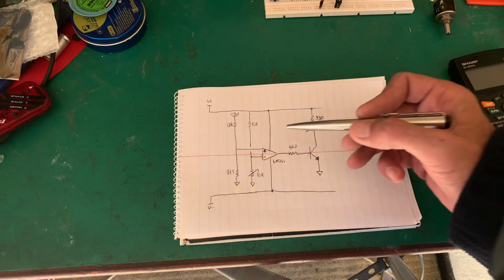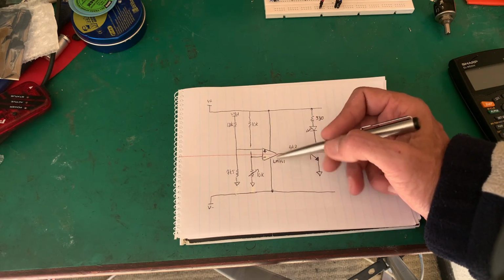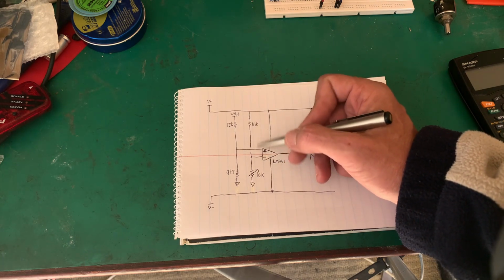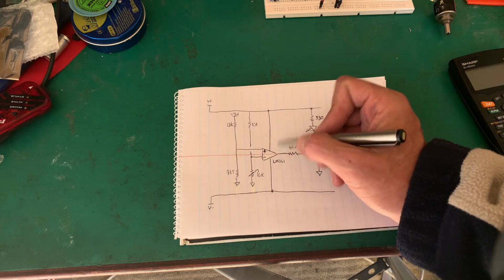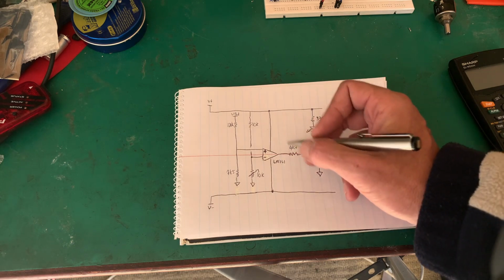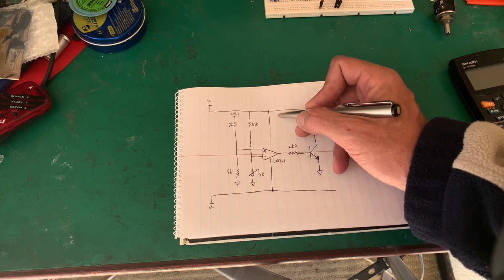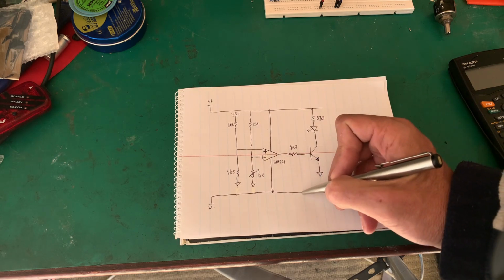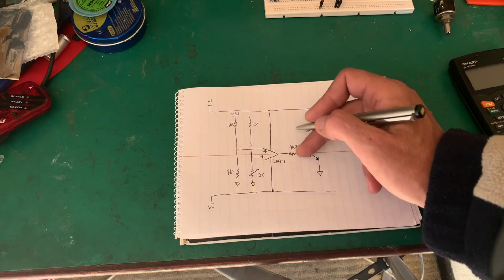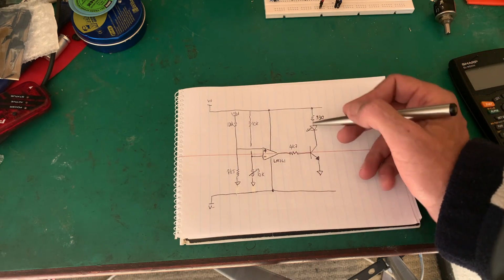Actually very simple. There's no feedback. Well, if we follow our rules, no currents flowing in here, we know that the output will do whatever it can to make the inputs meet. But there's no feedback. So what's going to happen? This output's going to switch high, or it's going to switch low. It's going to be on or off. No feedback. So it switches high and it hopes these two inputs will come back, but there's nothing there to bring them back. Or it switches low.